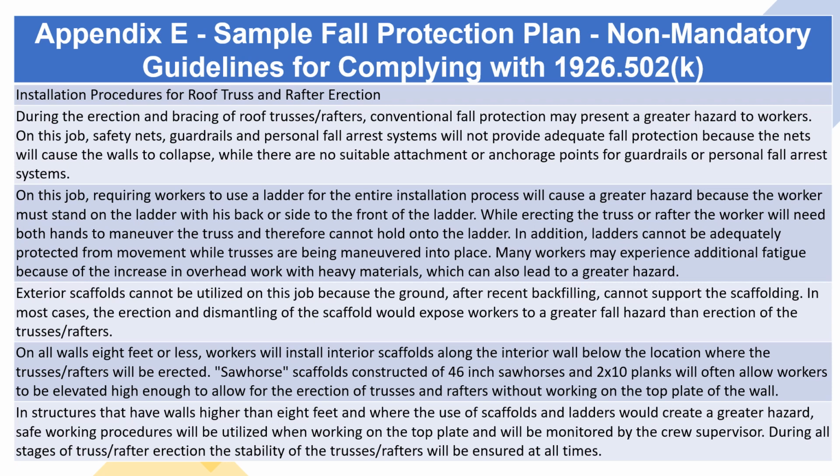Many workers may experience additional fatigue because of the increase in overhead work with heavy materials, which can also lead to a greater hazard. Exterior scaffolds cannot be utilized on this job because the ground, after recent backfilling, cannot support the scaffolding. In most cases, the erection and dismantling of the scaffold would expose workers to a greater fall hazard than erection of the trusses/rafters.